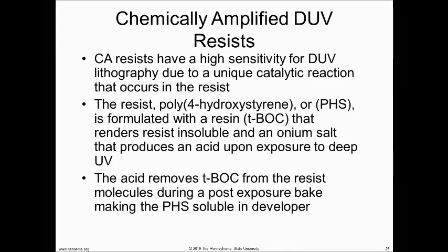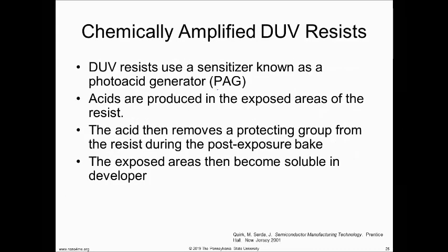So the chemically amplified resist, what we're going to do with these is a 2-step process. And it's a 2-step process because of that crazy drawing I did. We need to have the resolution on each individual die, so we can only afford to do one at a time. If we try to do the whole wafer, it won't be near perfect. So what we do is we focus on one little piece and make it really, really perfect.